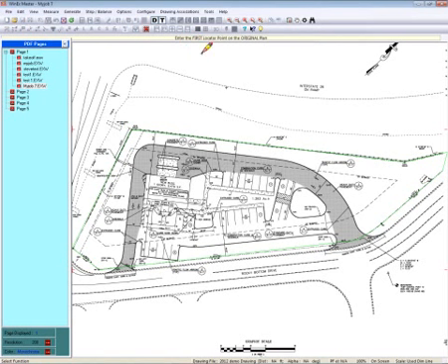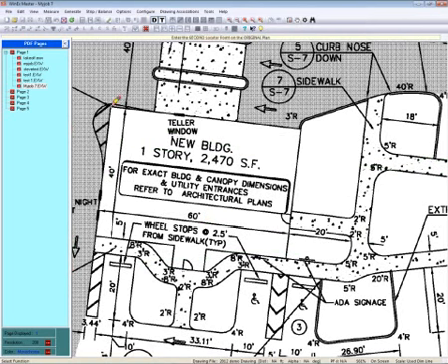And now the prompt bar wants me to enter 2 locator points on this page that I know are on the other pages so that we can match up the scales and the orientation of the drawing. So just like I did in the CAD file, I'm going to put 2 match points on here. And I'm going to zoom in. Again, I like to use the corners of pads or wherever 2 lines intersect.